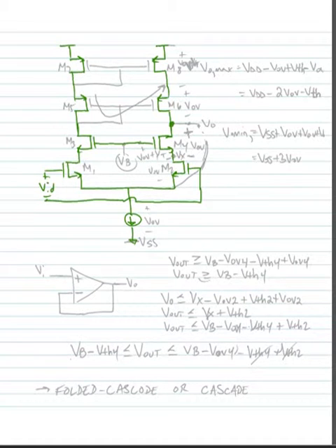So here we have our plus minus input differential voltage. We get our output voltage at this node. And we have to draw our current mirrors. And we'll connect these transistors to VB, some constant DC bias. So this is M1, M3, M5, M7, and M2, M4, M6, and M8. Alright, so what we might ask first of all is what's the maximum that the output voltage can be?